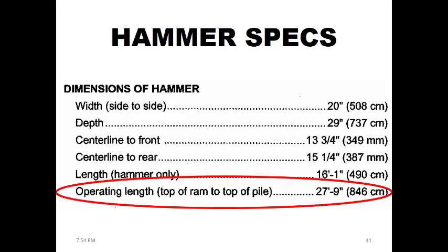Even though we mentioned that the piles can be in different dimensions, ranging, for timber, let's say 15 to 45 feet, right? Or let's say we have a 40 feet concrete composite pile that we need to drive. We have to pay attention to the height. In this case we have 27 feet and 9 inches, which will be a limitation of choice.